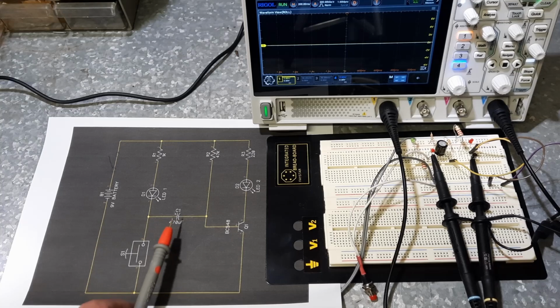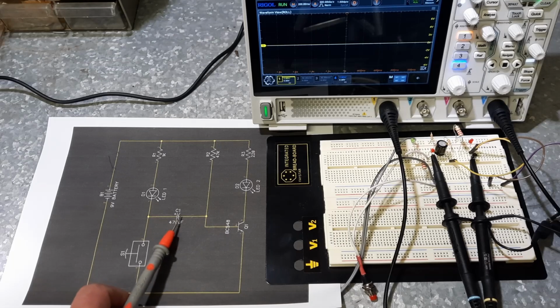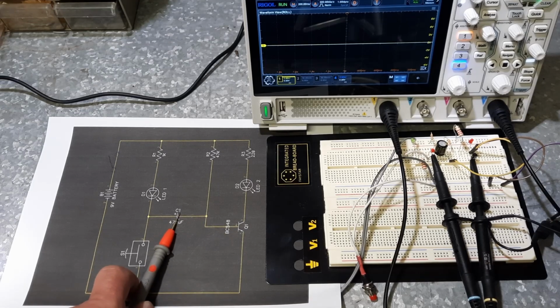And I know that we're not meant to reverse charge a polarized capacitor. In our case, we're using an electrolytic. Other ones are tantalum. But with that small reverse charge, the capacitor just doesn't get damaged. If you keep going with this in the reverse direction, as I said in the bit of paper before, where I pointed it out to you, yes, it will.